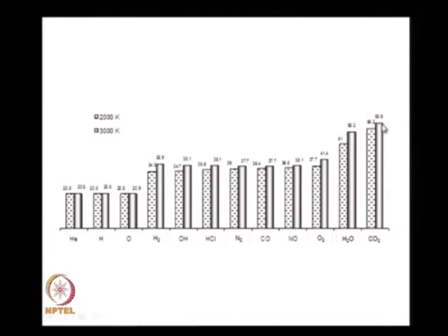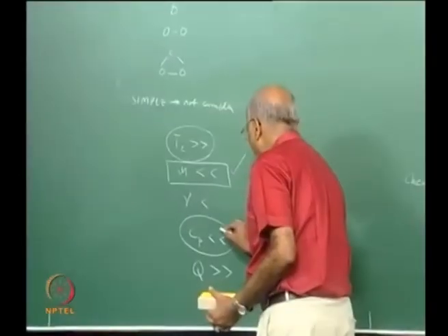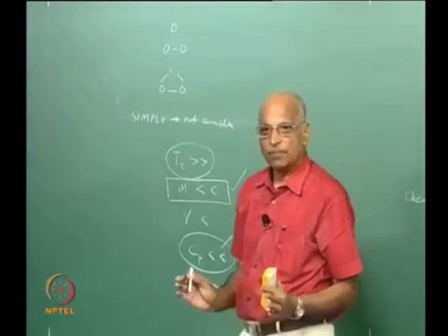This is the range. From this specific heat point of view, if my product gases were all dissociated into hydrogen and oxygen atoms, or diatomic, it is better. If I keep on increasing the complexity, my specific heat keeps increasing, and I will not be able to get a high temperature, and therefore specific heat must be small.